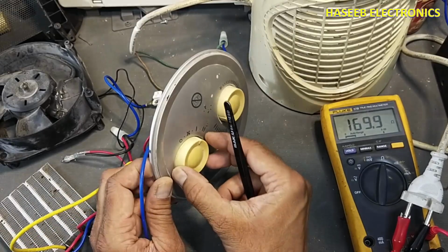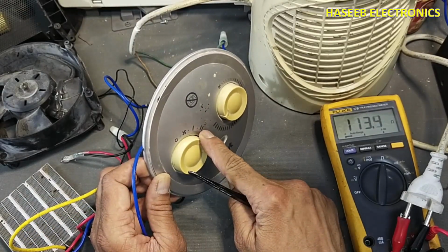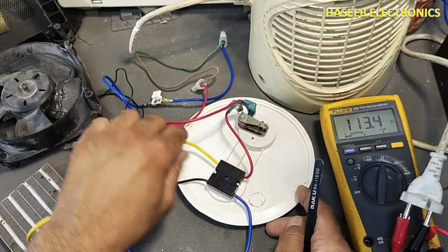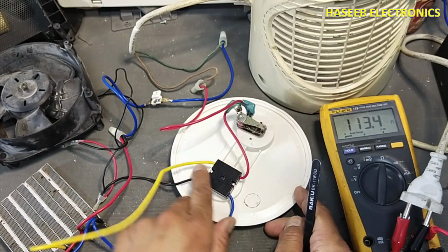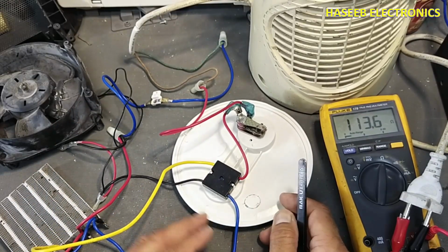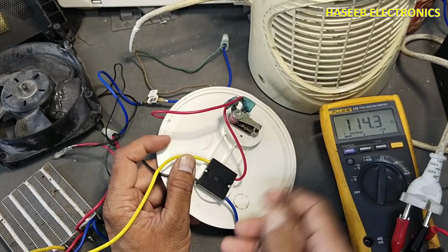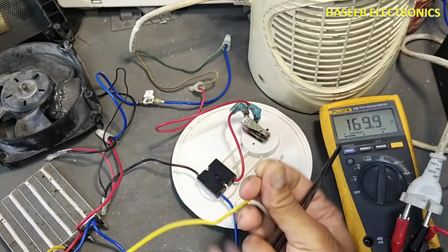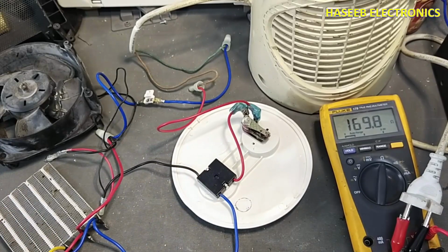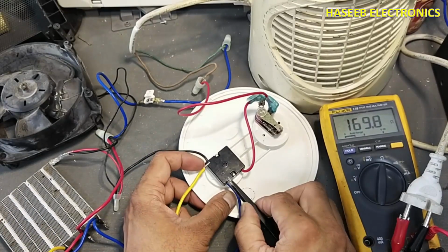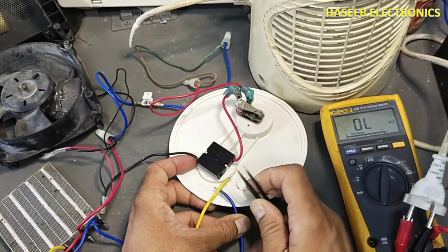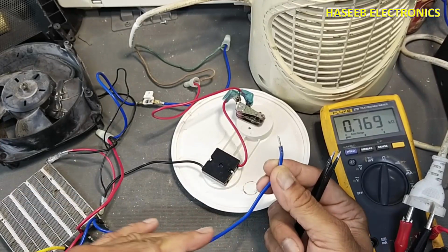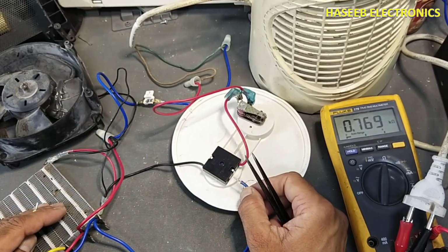Now move the selector to the last position, the full heat. At that time the fan, low heat, and full heat, all these sections will be connected to this line voltage. If we cannot find the dropping resistance, that is the 100 ohm resistor, maybe this line is open, or maybe the heater is open. If we cannot find the resistance at these heaters, that means we have a problem here. Maybe these lines are disconnected, maybe the heater is open.